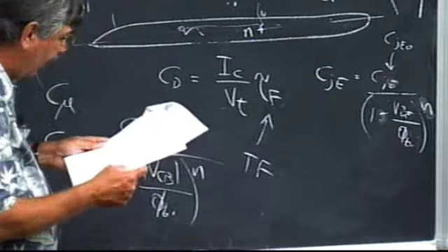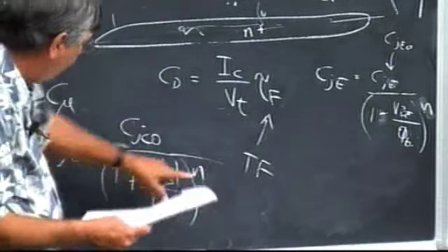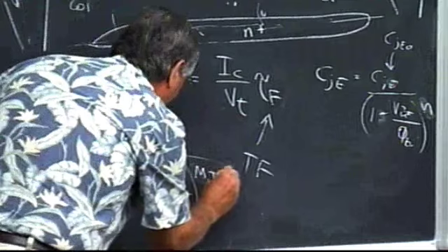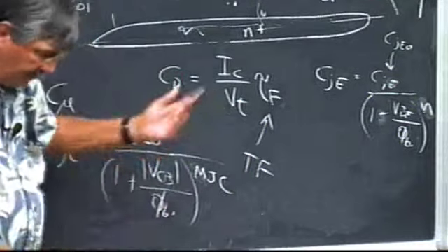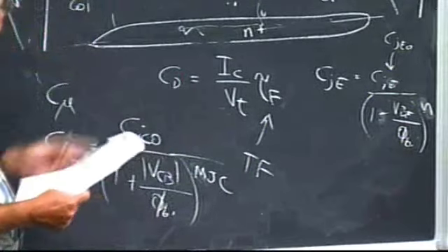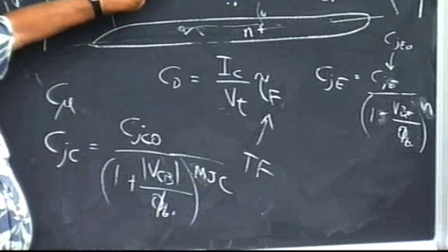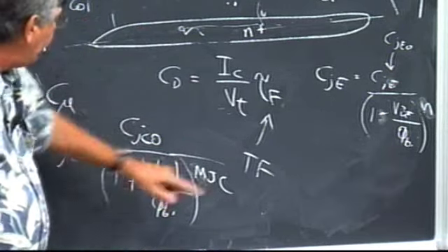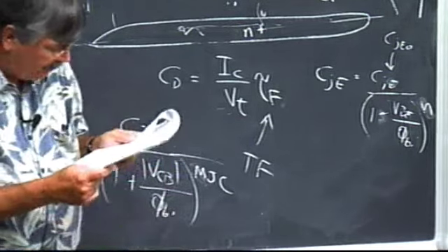There may be some other things that we can add. This thing here is actually called MJC, the SPICE parameter for that. Again, it's probably 1/2, typically, because this is uniformly doped. When the less heavily doped layer is uniformly doped, then you usually have 1/2 here. So there's a lot to remember, but you'll get it.